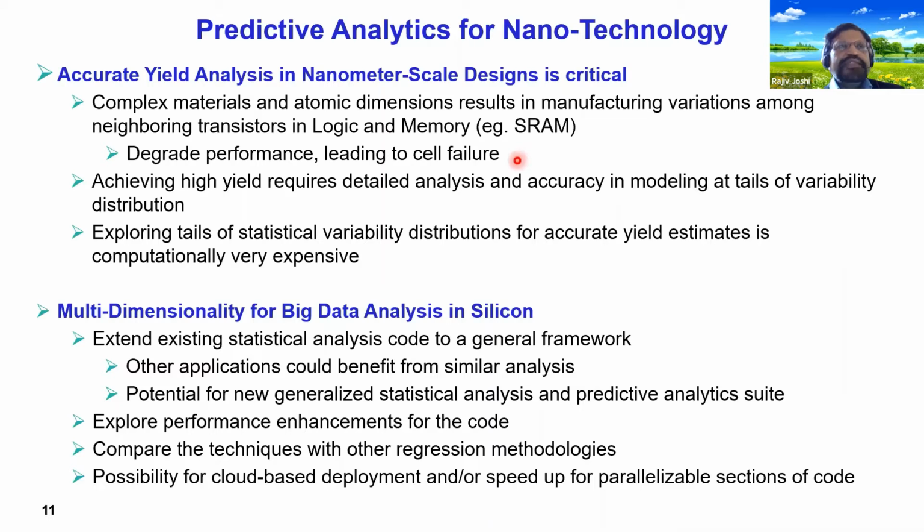But by the way, I can bring in the other topic, which is a separate topic of discussion, non-volatile memory. This is a volatile memory, but in non-volatile, you can do similar things. However, the parameters of optimization are different. So just keep that in mind, but similar techniques can be applied to non-volatile as well. And they will come in very handy in some of the topics that you must have heard, or that are emerging, like compute in memory, using the fancy emerging devices or memories like ReRAM, FeRAM, all kinds of PCMs, MRAMs, and things like that.